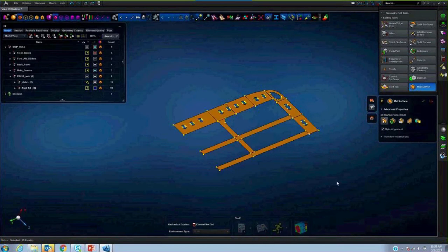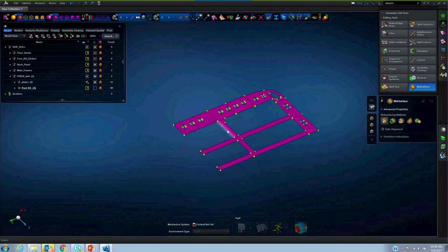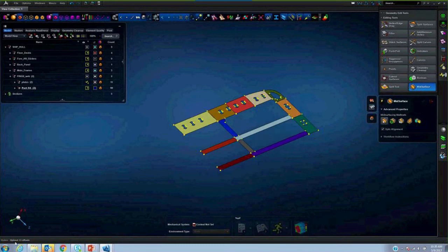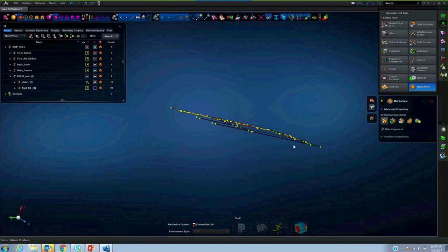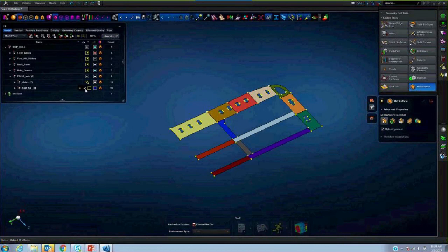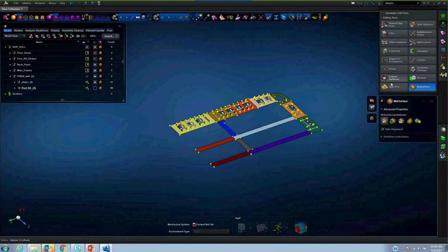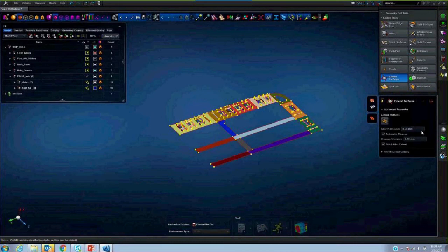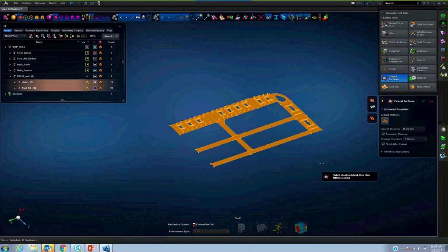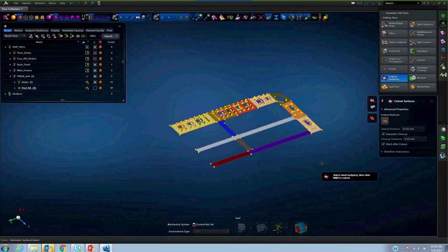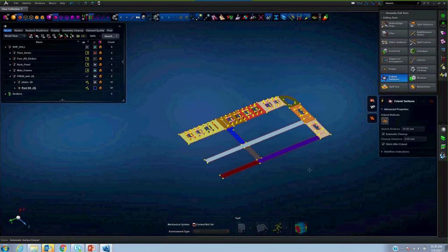And use up to alignment. Basically, I'm selecting all these surfaces. Then I'm going to select one of these as a reference surface to which it's going to align. That means all the 13 bodies or the surfaces are offsetted with respect to that one reference geometry. Now we should be able to extend all these parts. Let's take a look at extend all the surfaces. And again, I'm going to use about an inch as a tolerance, and maybe about 5 millimeters as a cleanup tolerance. And I'm going to extend all these bodies to kind of touch each other. Okay, all the parts are extended together now.